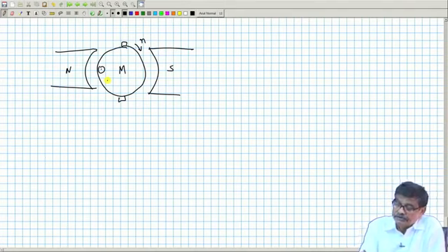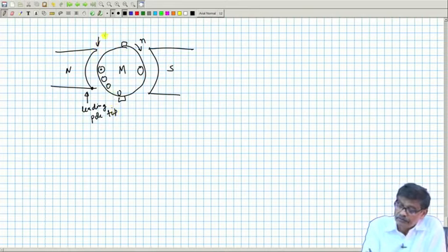Suppose he says that it is operating as a motor, running in this direction. Then the first thing I will do is, electromagnetic torque has to be in this direction. Therefore, I decide about the current by applying the left hand rule. Which one is the leading pole tip? This one is the leading pole tip, because these are the conductors, it is moving, so it will first see this one. This is the leading pole tip, and this is the trailing pole tip.